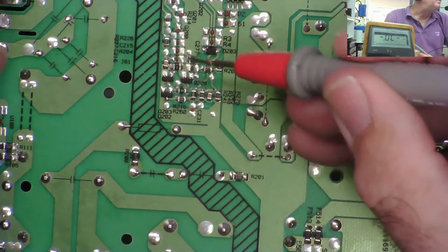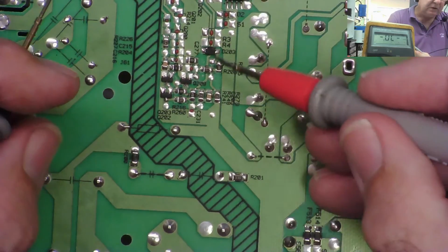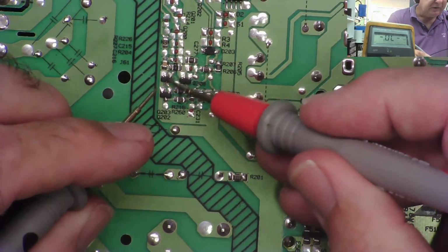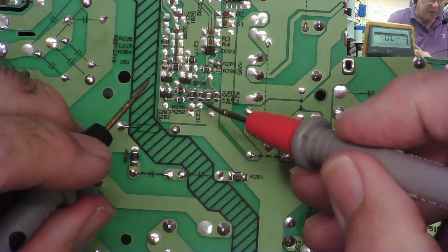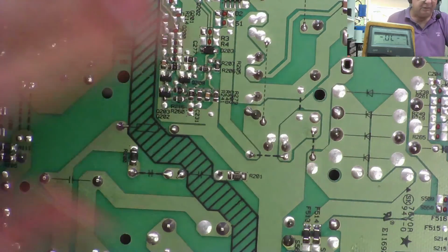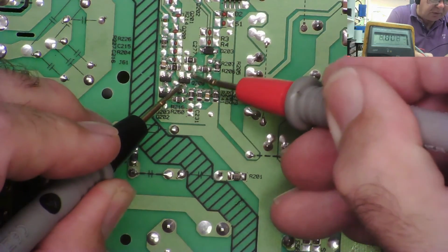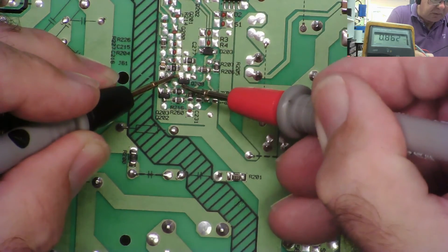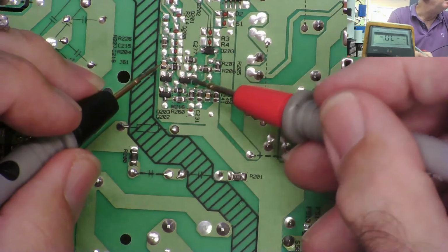So the only way to be sure of that transistor, if you suspect it, would be to take it out of the circuit, desolder it, test it and put it back. Yeah. You can easily clip your little component analyzer on these if you've bought one of them €5 things I'm going to buy. So that's how we can test them in circuit. Sometimes it's inconclusive and you can't say for sure, but you'll certainly find short circuits this way. See, again, that reads both ways across there. So to be certain, you'd have to take it out.